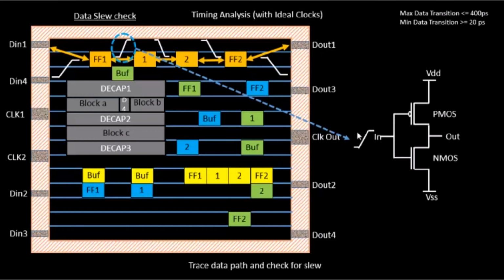What we'll do is feed this particular input waveform to a CMOS logic. And why CMOS logic? Because CMOS logic is the one that is being used to make most of the logic gates. And there are reasons for it, because when your PMOS is turned on, your NMOS gets turned off, and vice versa. And because of that, there is a lot of power saving. We'll talk about why we use CMOS logic in a separate section. Let's try to understand what happens when we feed this particular waveform to a CMOS logic.